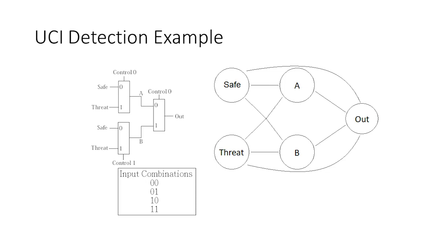But in other words, what you see here is 3 multiplexers. A multiplexer is a logical device that allows switching between 2 inputs based on what value the signal is. So on the top left and the right side blocks, we have 2 multiplexers that both have a control input of control 0. Depending on the value of the control input, the multiplexer will switch to either 0 or 1 and allow the signal corresponding to 0 or 1 to flow through its output.